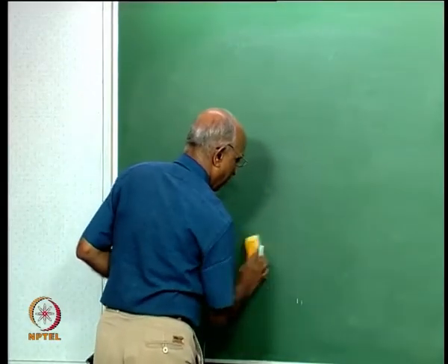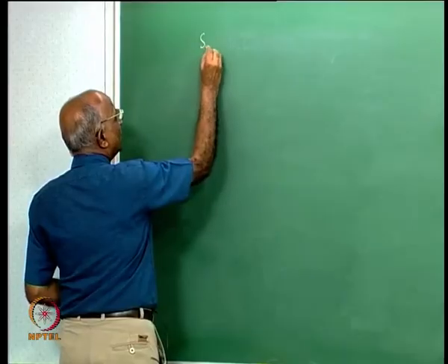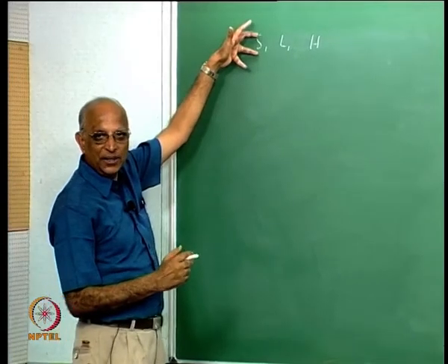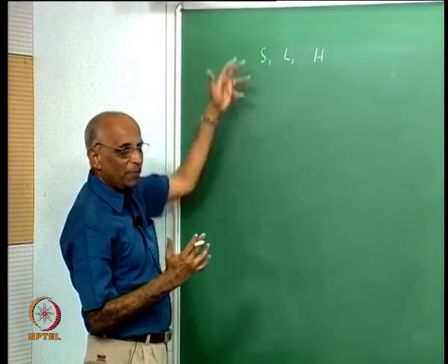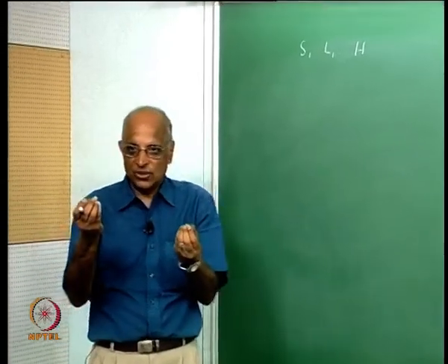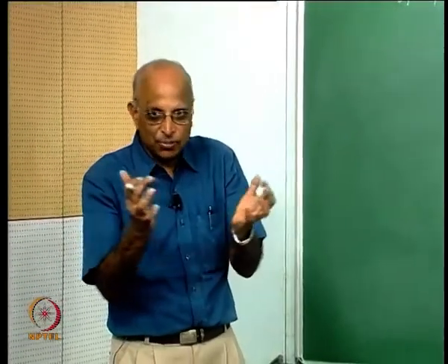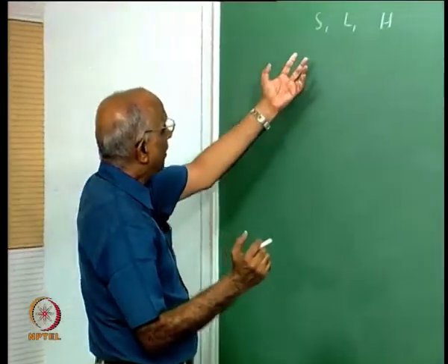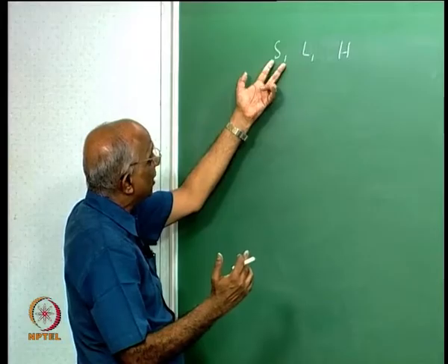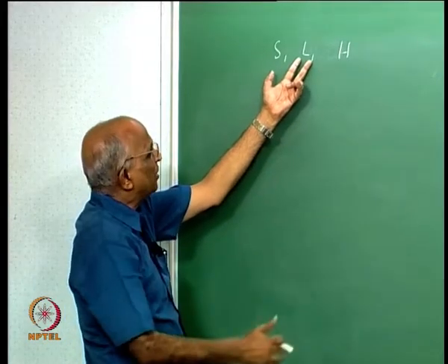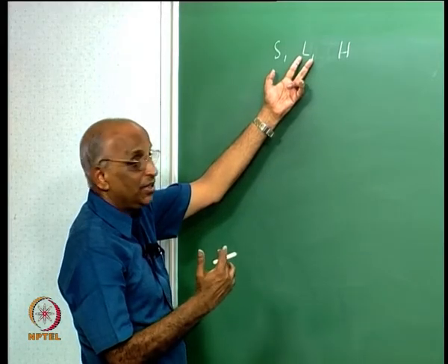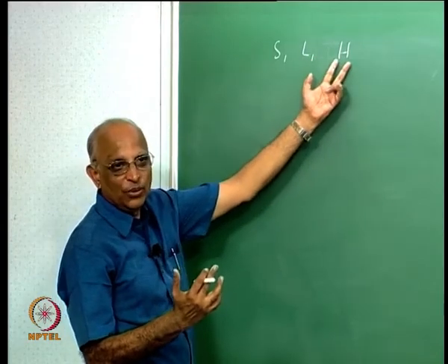To summarize the whole thing again, let us put it together. Propellants could either be solids, liquids, or hybrid. We classified solids into 4 categories: double base or single base; composite, in which you have crystals of solid dispersed heterogeneously in a material; a combination of composite and modified double base, that is double base and composite together; or nitramine. Liquids we just saw: space storable, earth storable, hypergolic, non-hypergolic. We said low energy, medium energy and high energy, and of course we looked at hybrid propellants.